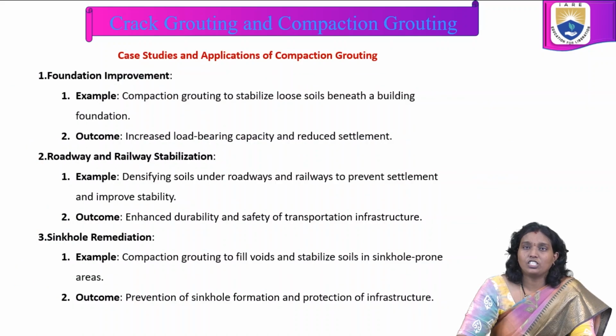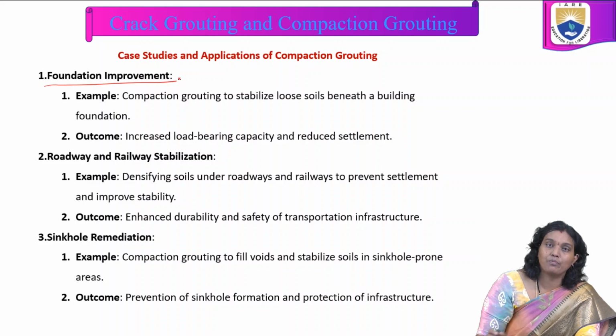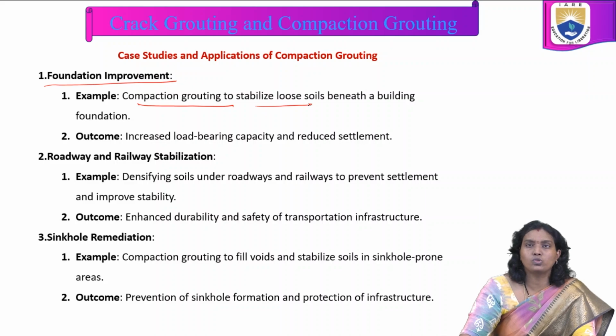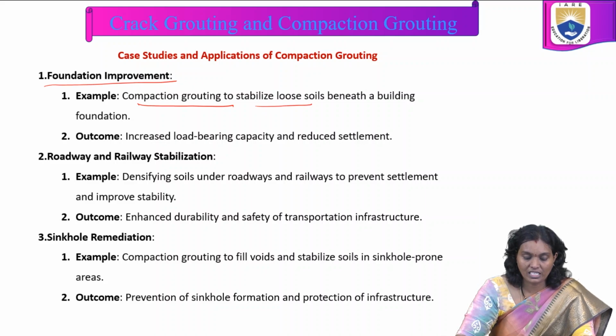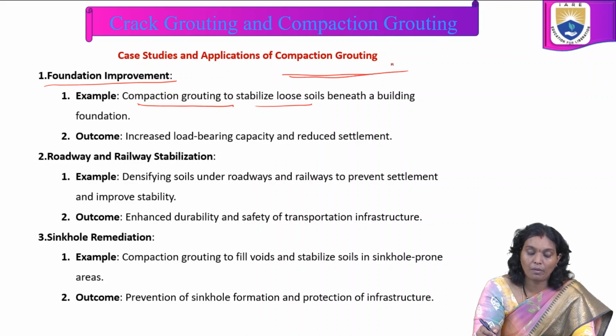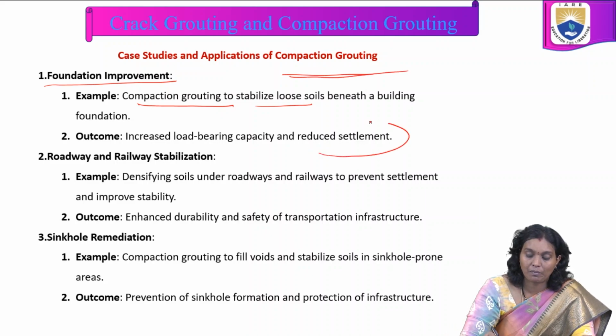Case studies and applications of compaction grouting. Foundation improvement: compaction grouting to stabilize loose soils under a building foundation. Its outcome, once we do this compaction grouting, is an increase in load bearing capacity and reduced settlement.